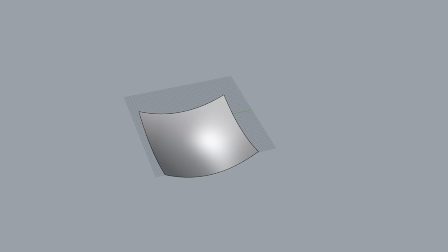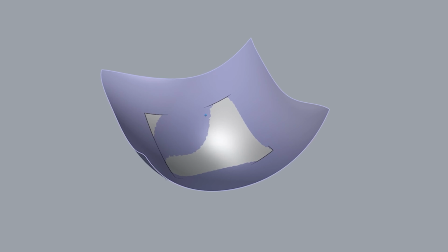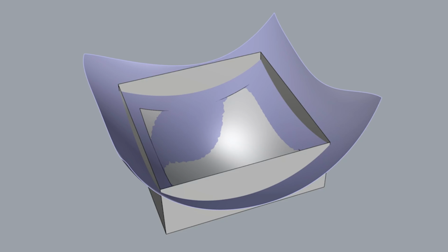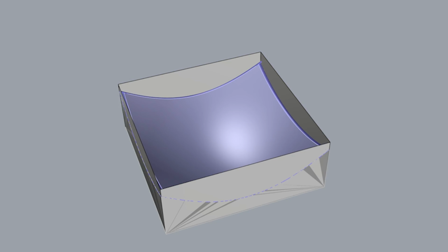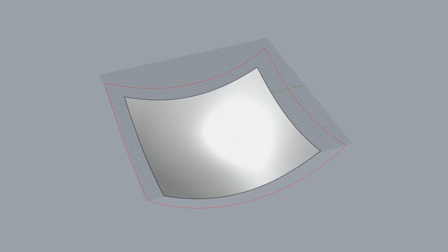We start with a given design surface and a panelization of that surface. Now let us take a closer look at one of these panels. We take the panel geometry and approximate it by a larger quadratic Weingarten surface. We use the Weingarten surface in a box larger than the panel to get a set of 4 center lines of the pipe surfaces touching the Weingarten surface. These curves here in red are the initialization of our optimization process.